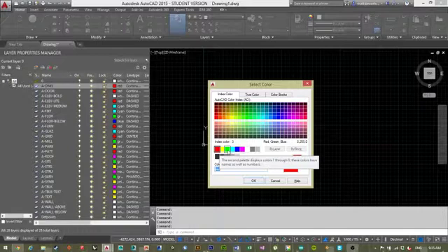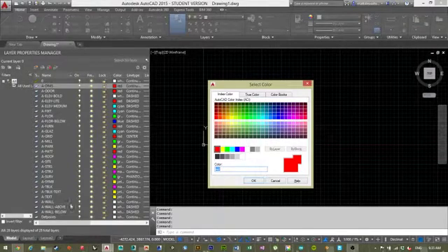That makes it super easy to do your thing in AutoCAD without even having to worry about line weights. You know that when I print it out, all my walls, which are white, are going to be the thickest. All my doors are going to be the lightest. And as long as you've kept your layers something that makes sense, there's absolutely zero work.